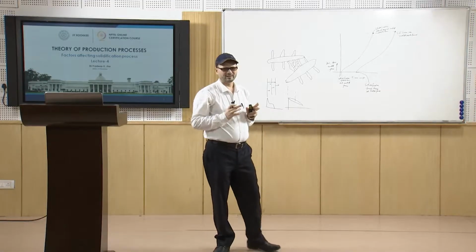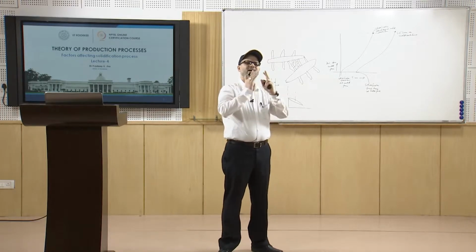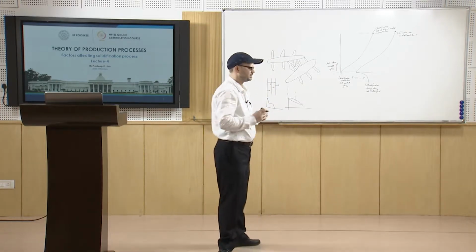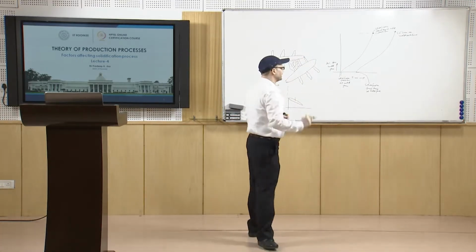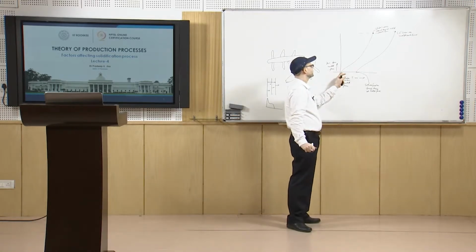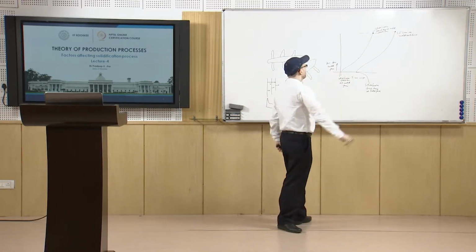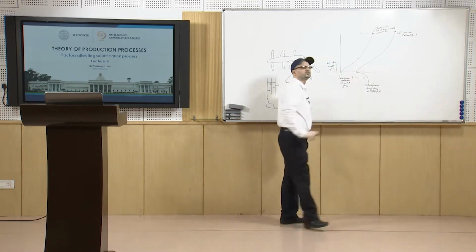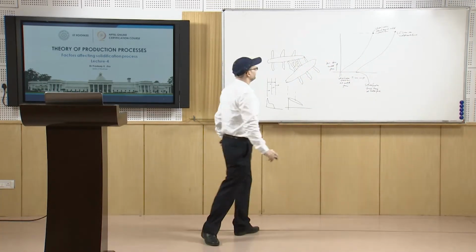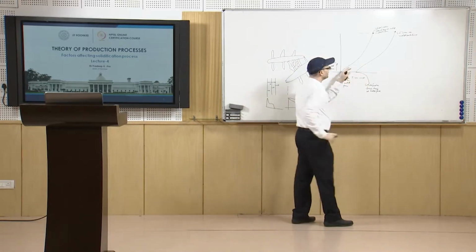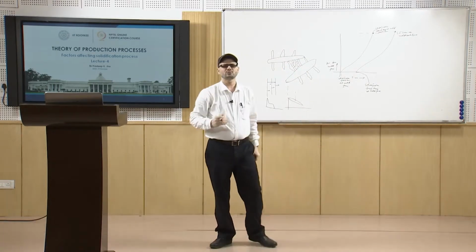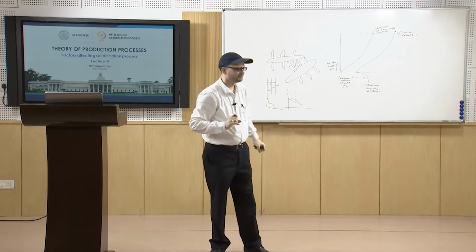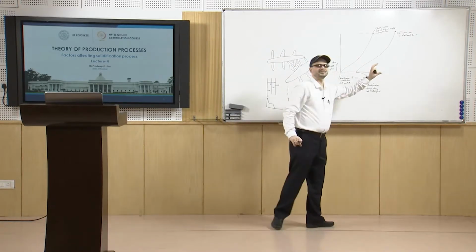Now, what we saw is that in the case of alloys, initially you will have the columnar dendritic structure. Initially, since the undercooling is maximum, the heat extraction rate is maximum, the temperature gradient line is the steepest one. In that case, you will have the start of solidification here quickly, and you will have the equiaxed grains here, very fine equiaxed grains. Then you will have columnar grain growth taking place. Growth is taking place in this fashion slowly, not near the wall, as we move further into the liquid metal towards the mold center line, and you will have the columnar dendritic grains.